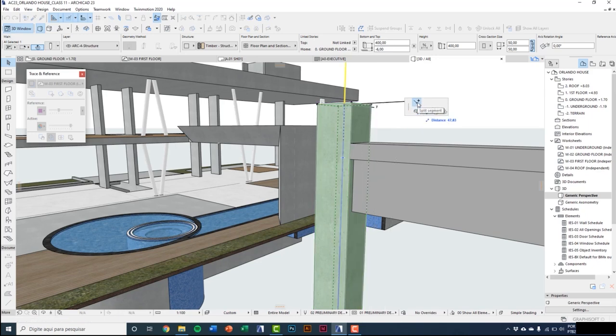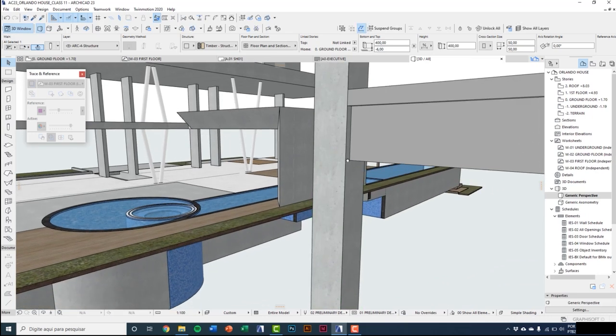And now click at the bottom part of the bin, the bottom part of this T profile, and after clicking again on the reference line, split segment, at the bottom part of the bin. And I'll click again to do another segment, and I'll type a distance here. So 30 centimeters.